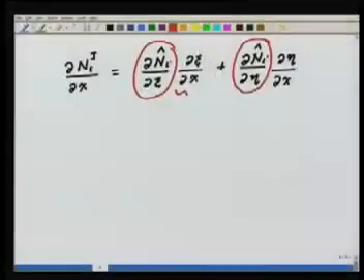These quantities we have to get from where? From the mapping. Okay, and remember that serendipity or tensor product, p order anything, we are talking of only linear maps of the geometry. Okay, the mapping is independent of the order of approximation for the problem cases that we are talking about. Okay, so this, where will it come from?